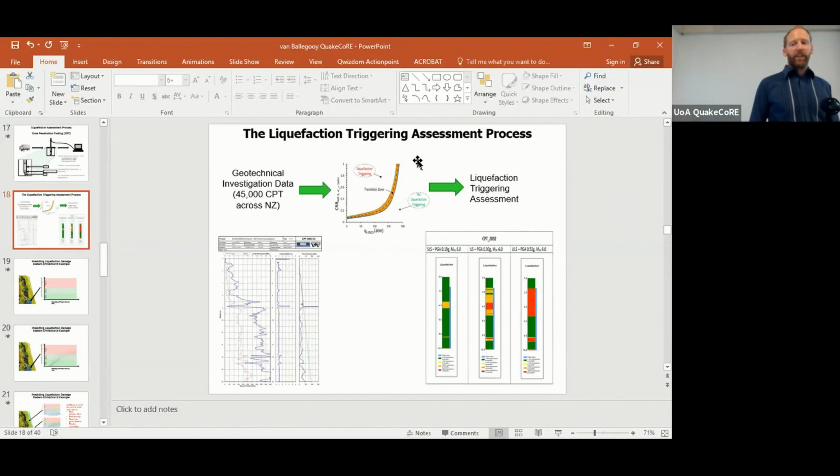Now, the nice thing is that this framework has been able to evaluate whether those corrections are indeed doing a good job, or when we have silty soils, whether there are a lot of false positive and false negative predictions going on. So we can once again scrutinize not only the performance in sandy soils, but also in silty soils.